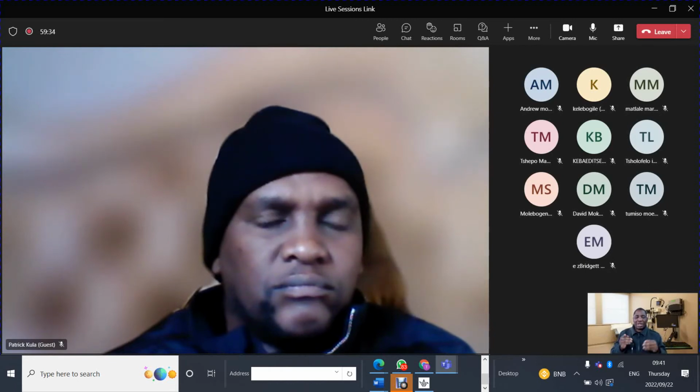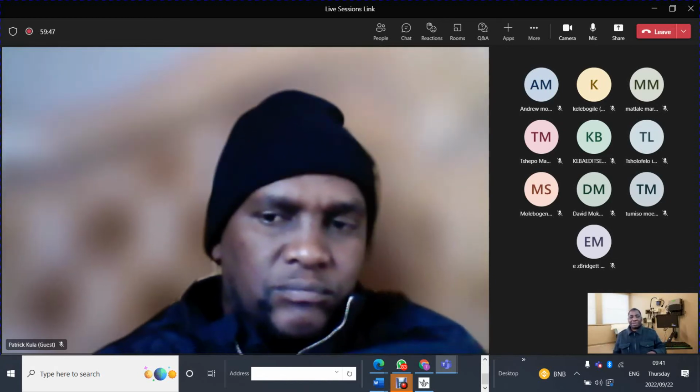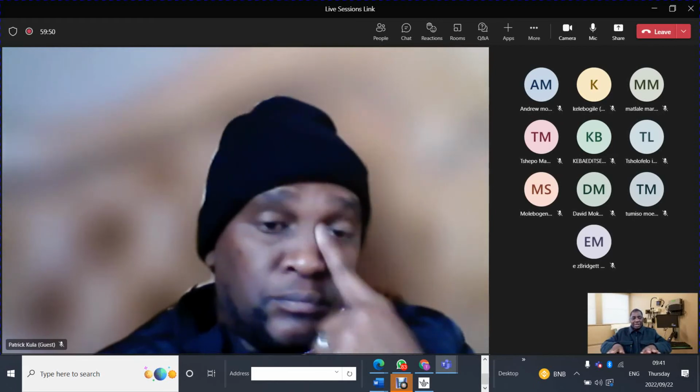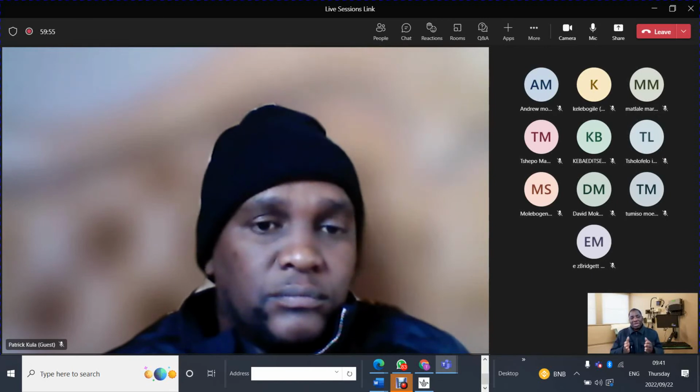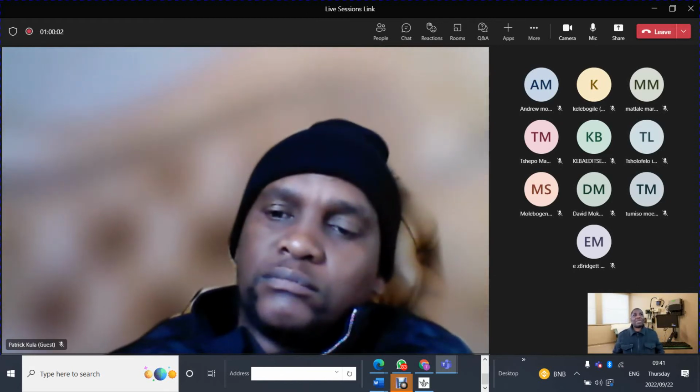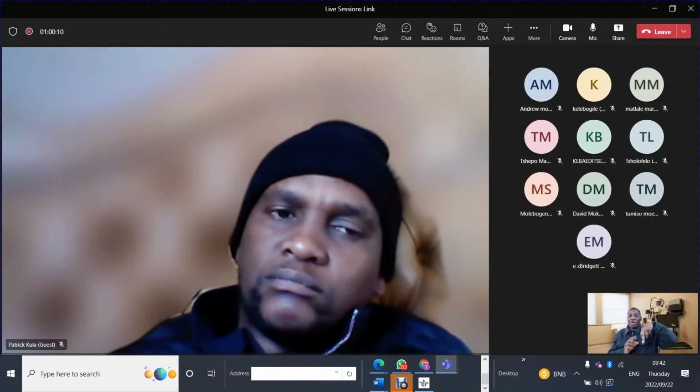At the active electrode, it is concentrated at the tip, so you can cut and coagulate. But at the passive electrode, because of the size of the electrode, it is dispersed. The current density is less, so the heat is dispersed and you only get a warm sensation. But when you reduce the cross-sectional area, it's like someone wearing a flat shoe versus someone wearing a high heel that is very pointed, like those stilettos.